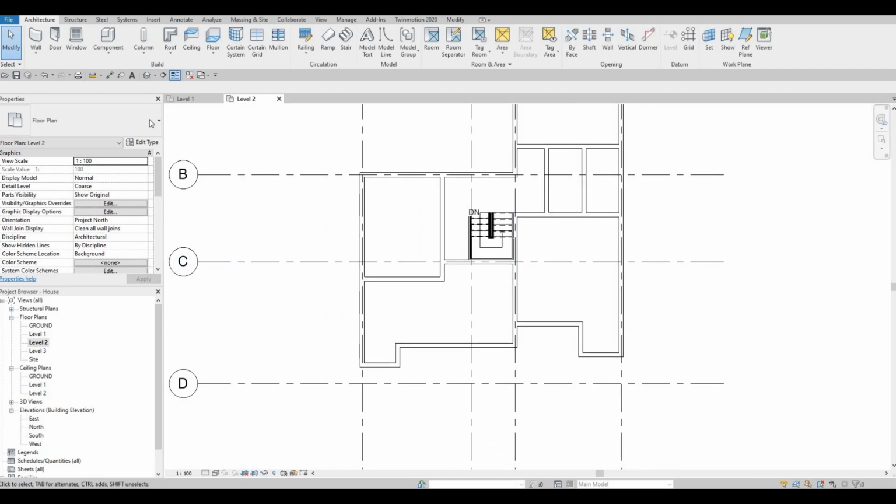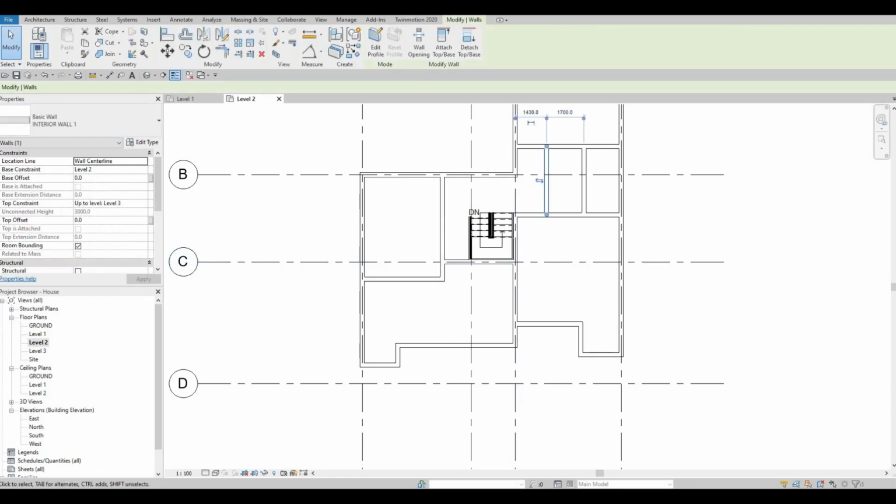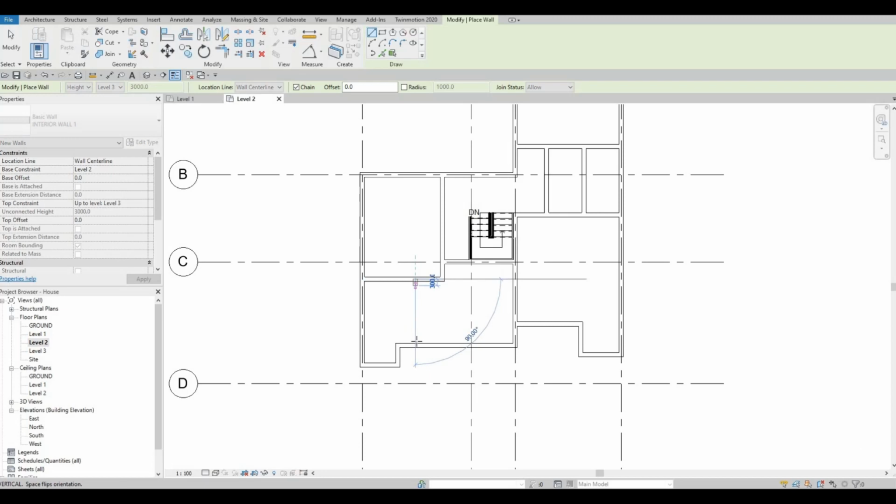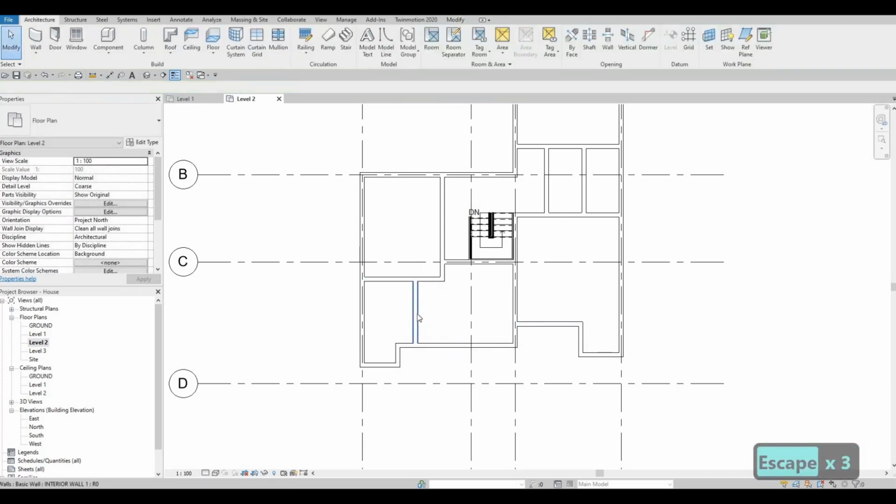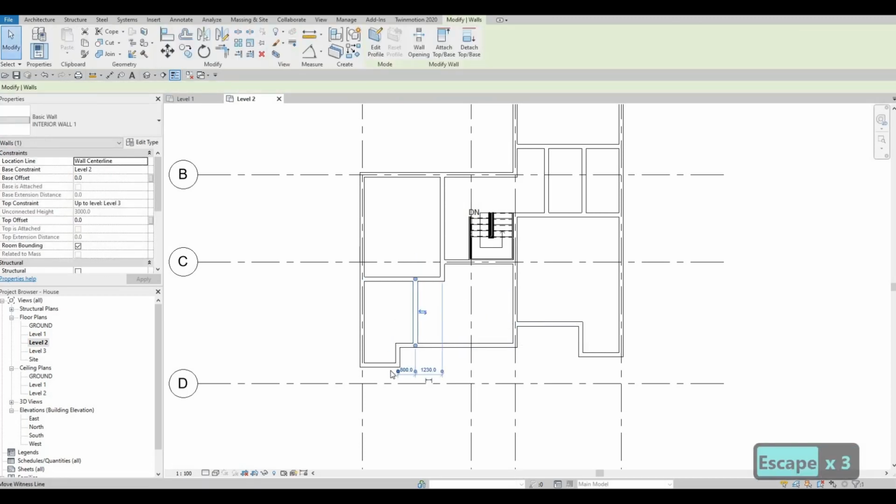So after that, let's add in some walls right here. This wall. So here, select that, CS. I'm going to add a wall right about here. And then select this, and then grab this one and put it right here. I want this one to be around 2700.